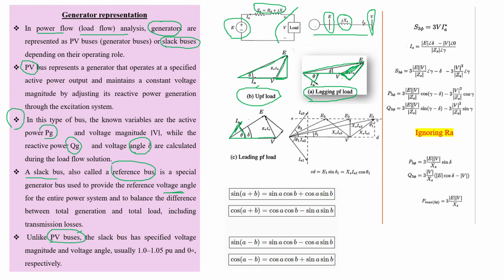So this is the voltage drop due to the resistance part of the impedance, whereas the voltage drop due to reactance is perpendicular to the current. And this is the internal voltage. This internal voltage should give the sum of these voltage drops plus the terminal voltage. Again, we can calculate the magnitude of internal voltage drop for a power factor.